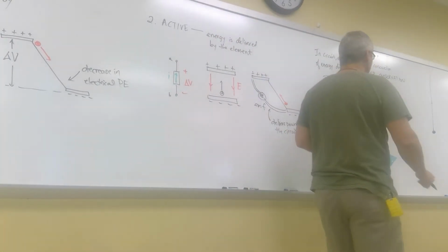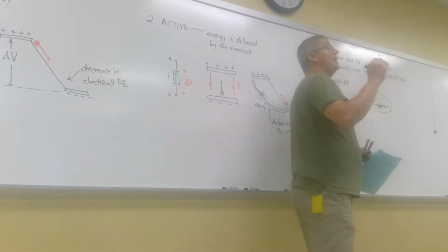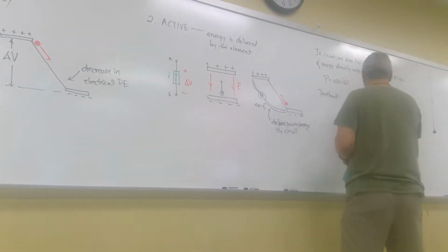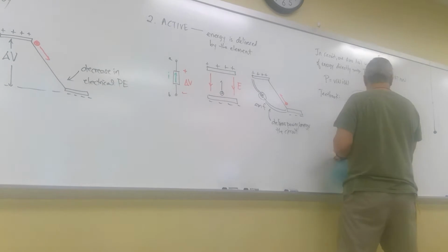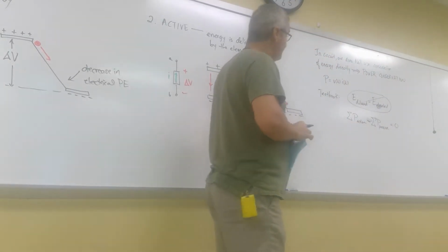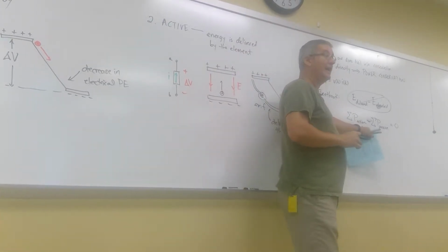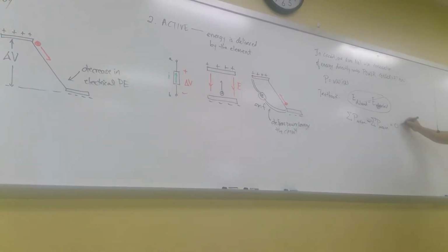But because, as I said before, energy is typically very challenging, what we do then is we talk about the power delivered by the circuit. The power that's active, all of the active sources must sum such that all of the passive elements must sum to zero. And this is a very common way of looking at this thing. What I find here is that this explicitly forces you to deal with the minus sign. So when I do it personally, I always say that all of the active sources must equal all of the passive.